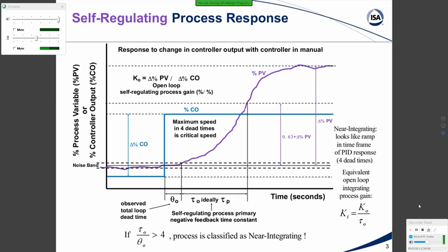That's kind of an interesting situation. If you look at the ordinary differential equations, which you probably won't do, in any of my appendices, you can understand for the generic form what's happening at the very beginning. There's this ramp rate going on according to the time constant, or for a true integrator according to the integrating process gain, and you can convert back and forth using that very simple relationship here.